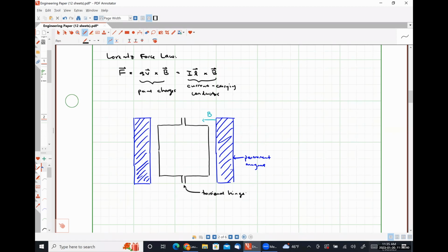Okay. So the top of this plate is polished because it's going to serve as a mirror. Okay. So effectively, we have a mirror attached to a torsional hinge. So it's a scanning mirror, and it's going to reflect depending on what our torque that we were able to induce in this thing is doing. On the back of the plate is a planar coil.